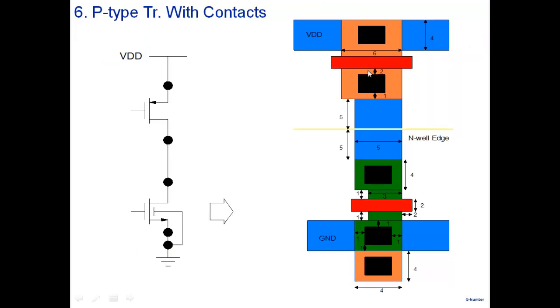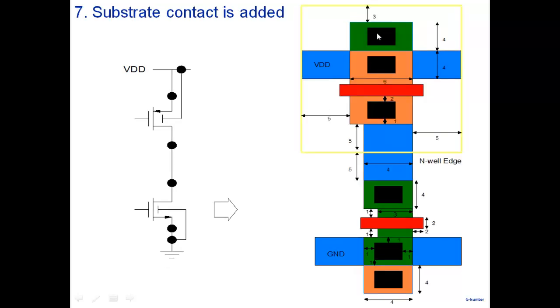And now I make similarly the PMOS transistor. Note, very similar, but it's of a different dimension. The dimension here is 6 lambda, because PMOS was 6 lambda. Dimension is different. And this is VDD. Minimum dimension of this is 3 lambda. I've chosen it 4 lambda here. And this is there. Next, let me add a body contact here. Body contact is also added. Now, this is the N-well where the PMOS is fabricated.